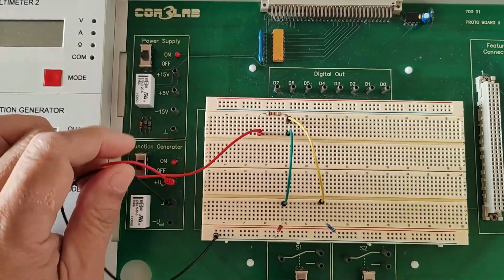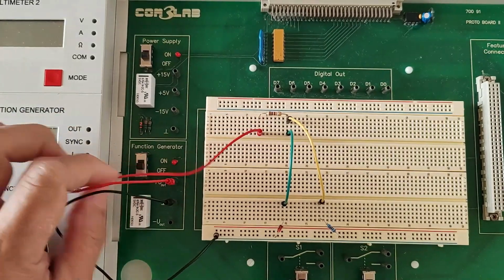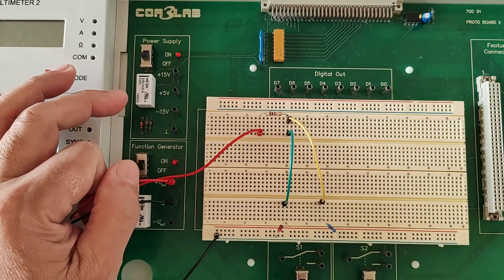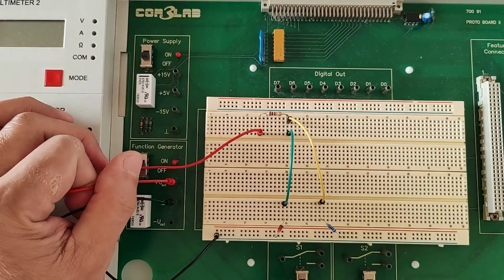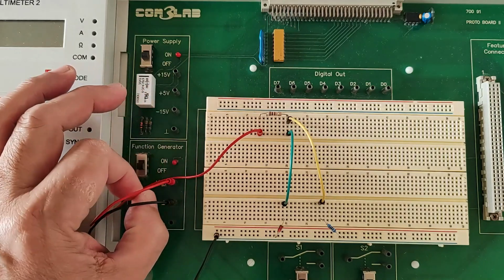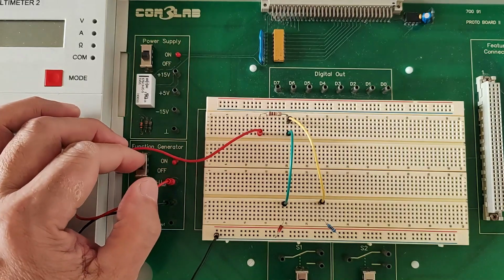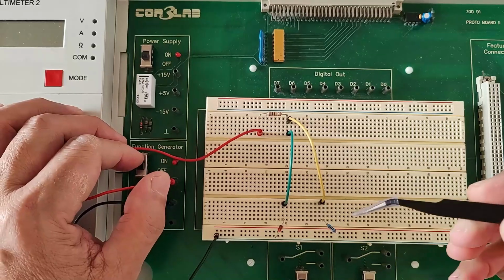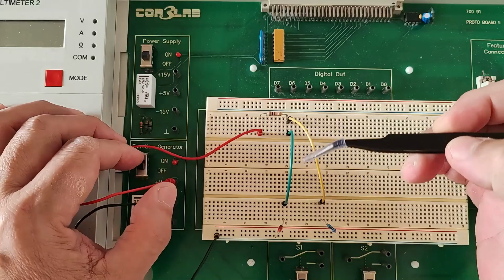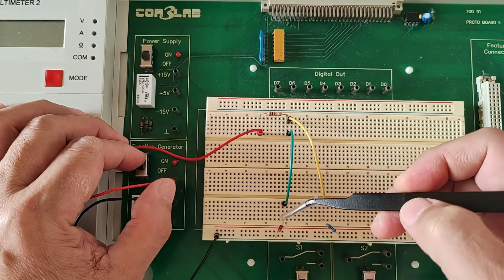As mentioned previously, what we will be doing here is that we will first set our variable DC supply voltage to a low value, maybe 1 volt, and we will gradually increase it by increments of 1 volt until about 10 volts. And for each pass, we will be measuring two things on this circuit. First is the voltage across our load resistor here. And second, the current flowing through our Zener diode here.